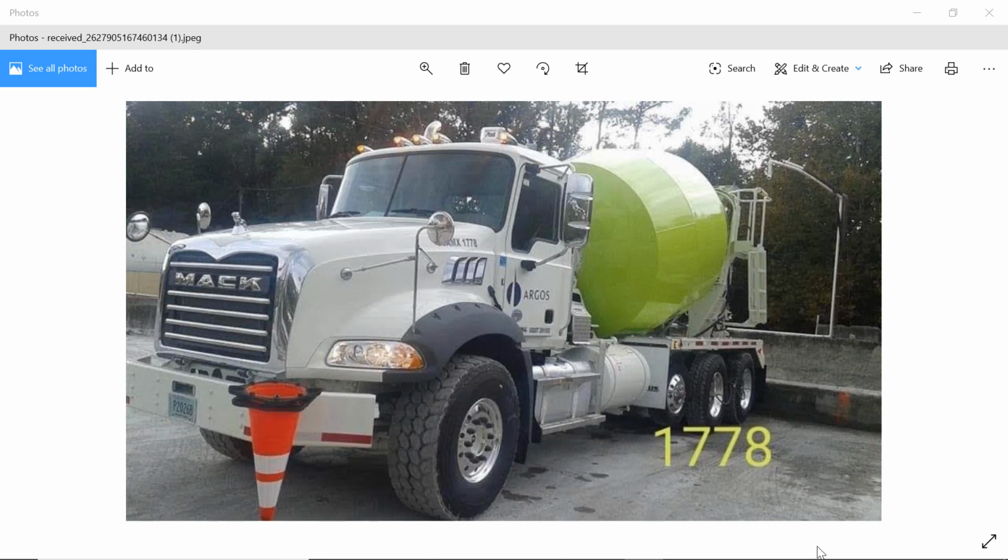Determine the moisture content as a percent of the aggregate dry weight. 100 times the wet weight minus the dry weight, divided by the dry weight minus the tare weight, is equal to the moisture content in percent.